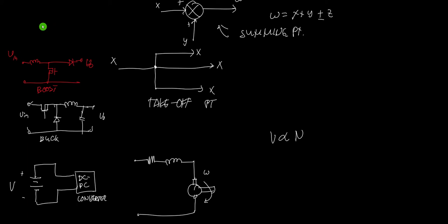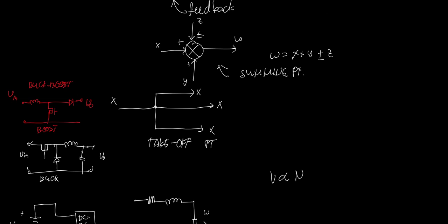For the combination, the inductor for a buck-boost. So this one is a combination of the two. It can be step up or step down. So the inductor will be in the middle. Then here we have the MOSFET or any switching mechanism. Then we have the diode here. And we have a capacitor. So this is a buck-boost. Example of a buck-boost. A simple buck-boost. So we have input and we have output.